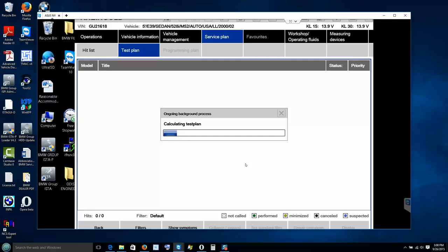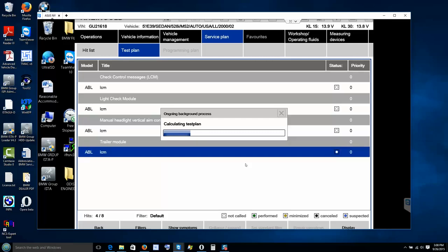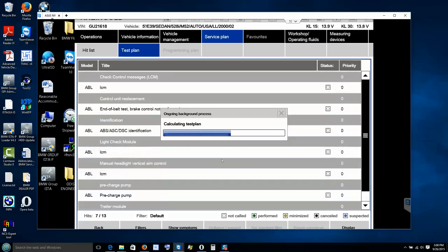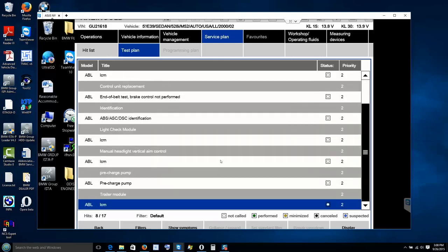Because the xenon light, whenever they move, they basically send information to the DSC, and then it calculates the angle of the light compared to the speed the vehicle is traveling. And then it looks at the steering angle, and then it can know the best situation to calculate so the vehicle does not spin off the road or lose control.